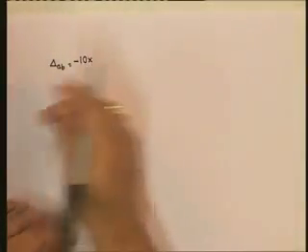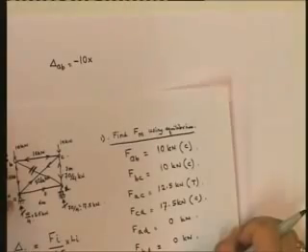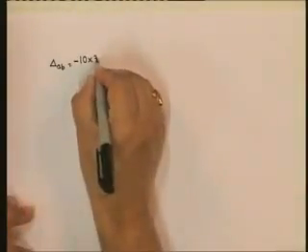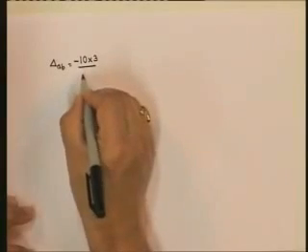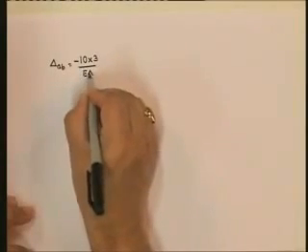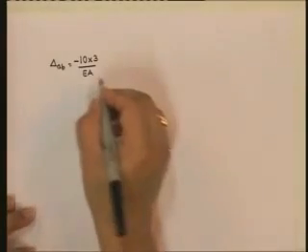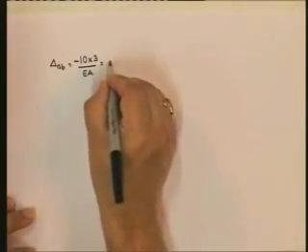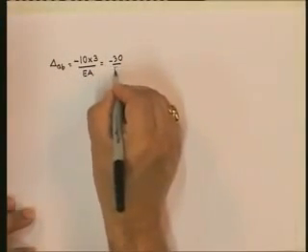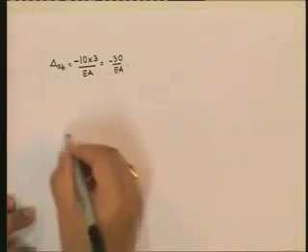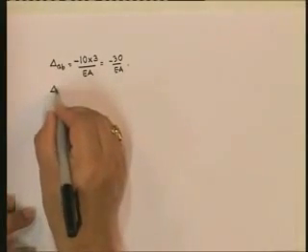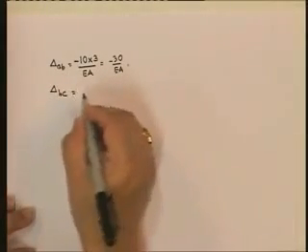What is Li? LAB. Let's look at LAB. What's the length of LAB? 3 meters. So it's going to be 3 divided by EA, noting that I have said that all EA are the same. So delta AB is equal to minus 30 upon EA.